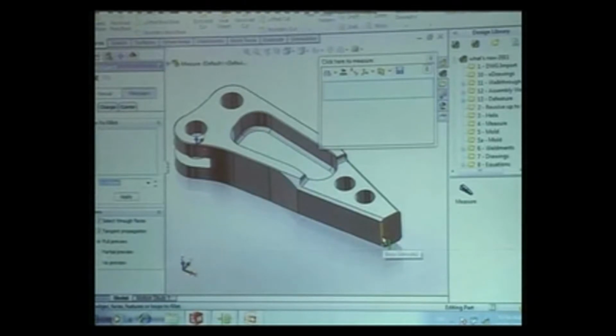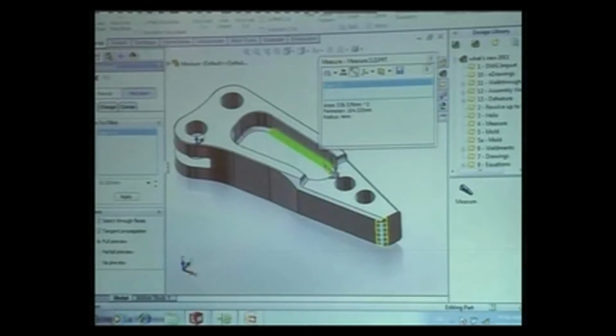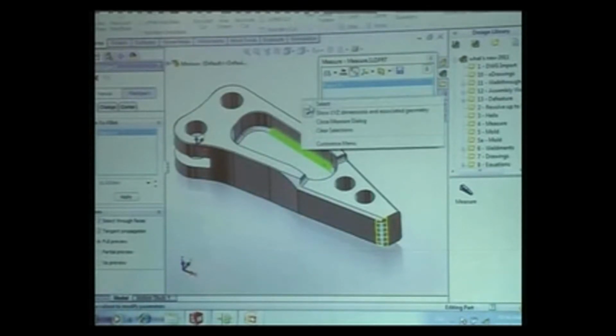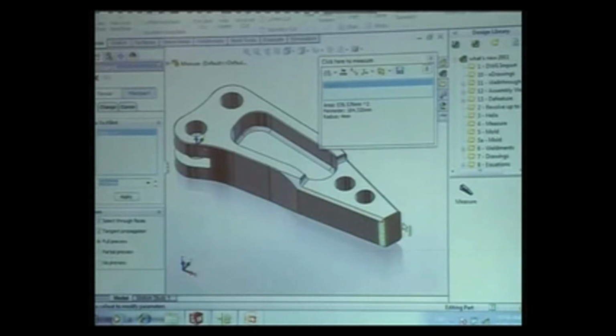Say I want to have a fillet of some radius along this edge, but that radius should be the same as what we have got here. For that, I can just quickly get back to the measure tool and find out the exact radius. It's very simple for me. Give the same radius here also and select some more edges where you need to have a fillet done.